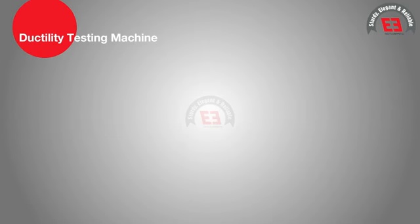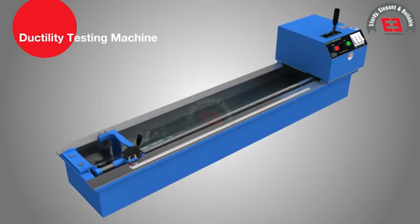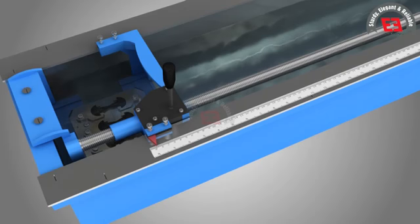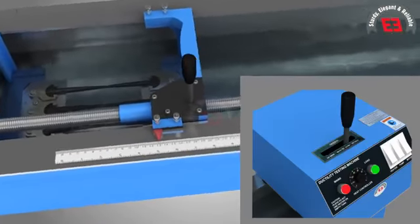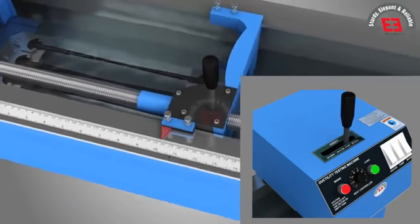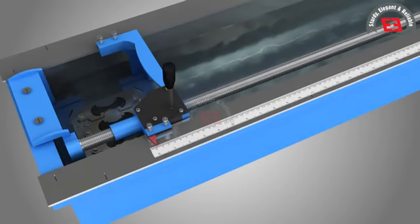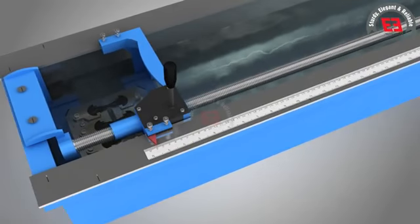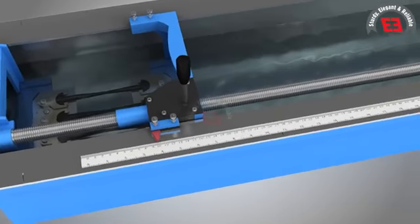Ductility testing machine. This apparatus is a constant water bath type with a pulling device at a pre-calibrated constant speed of 50 mm per minute and 10 mm per minute. The central rod of the machine is threaded and through a gear system provides movement to the ductility molds, the clip of which is fixed at one end, and the second clip stretches the thread of bitumen binder away from the first clip.